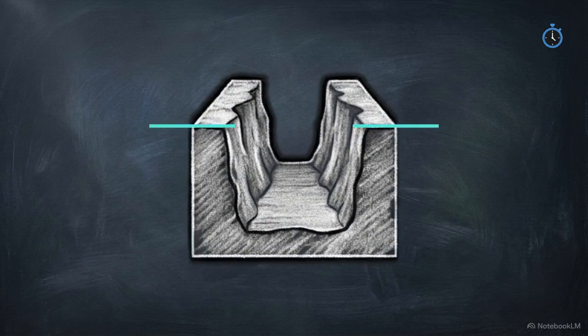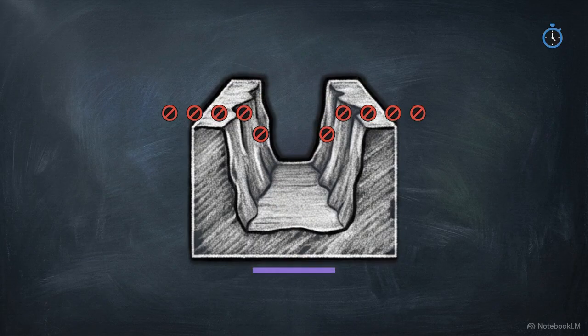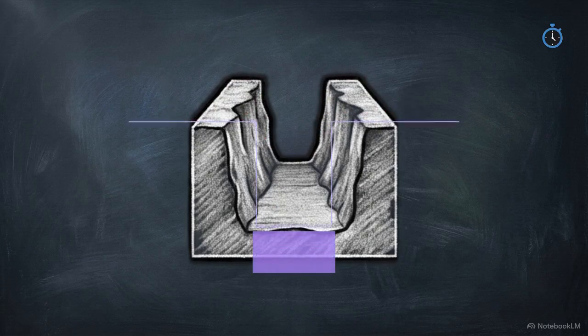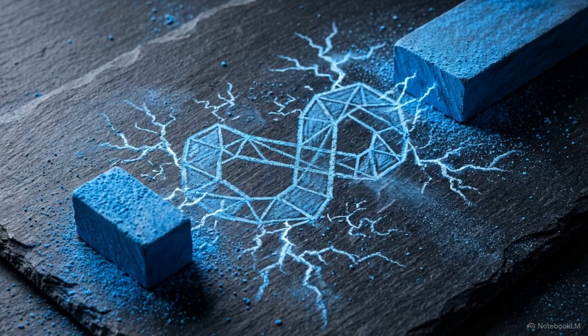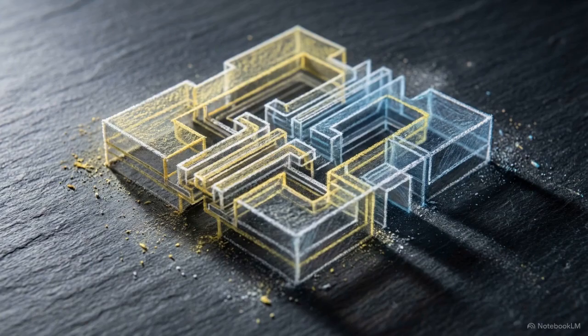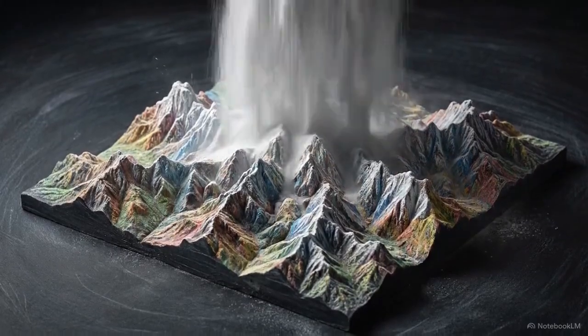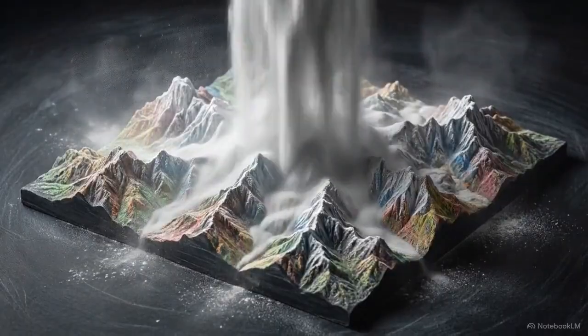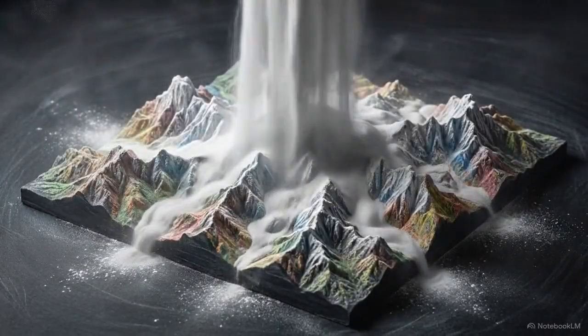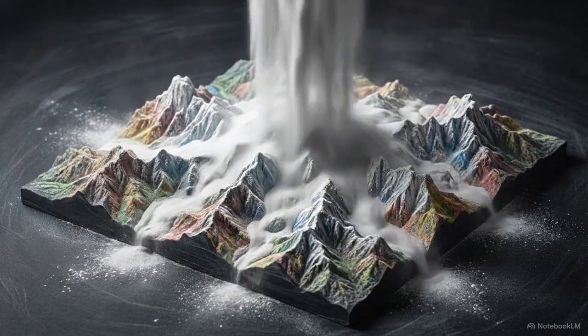Timed pulses intentionally inhibit film growth in overexposed areas of the substrate, giving the chemical reaction in the underexposed areas time to catch up. These temporal gating methods are strictly necessary for depositing ultra-thin crystalline electron channels. Growing precise beta gallium oxide films is currently required to manufacture next-generation 2D metal semiconductor heterojunctions. By replacing continuous streams of chemistry with discrete, time-gated steps, engineers circumvent spatial shadowing and achieve mathematically perfect conformality, regardless of the underlying topography.